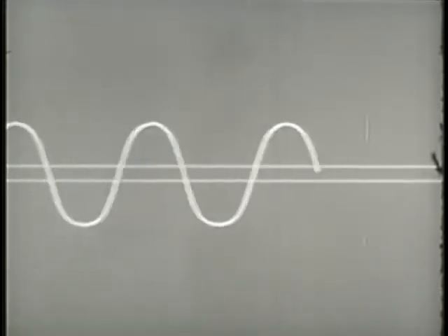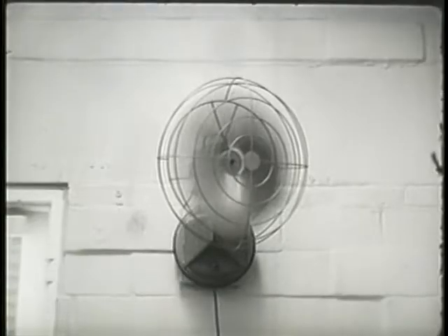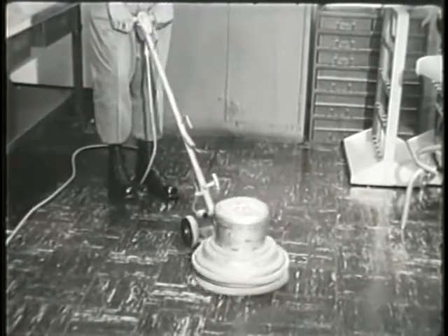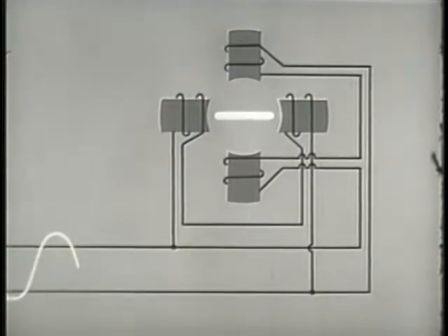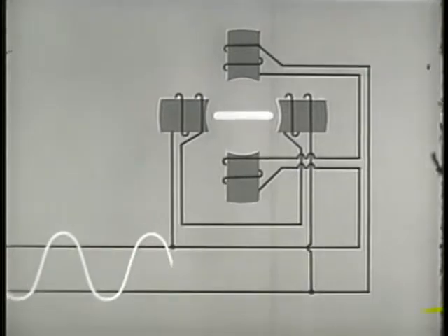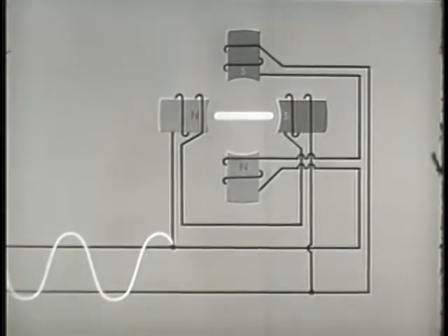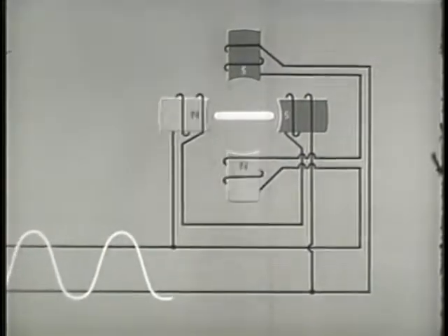The most common type of current available in most sections of the country is single-phase AC. For that reason, single-phase induction motors are widely used for many and varied purposes. In the single-phase induction motor pictured here, the single AC output energizes both sets of poles simultaneously. There is no phase difference in this arrangement, and so the field will not rotate.